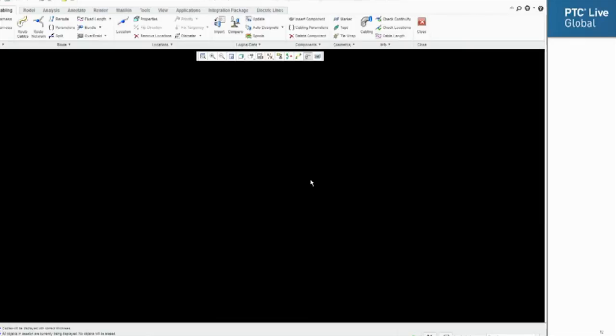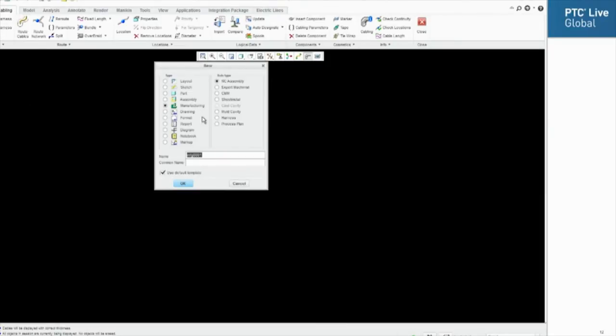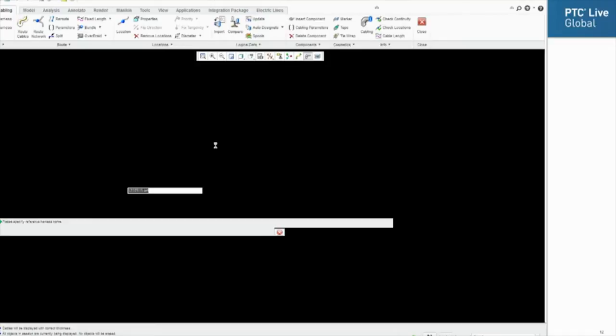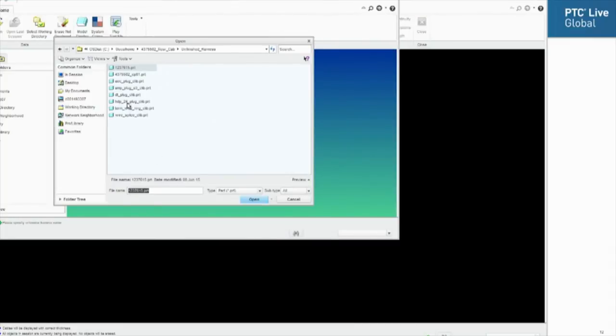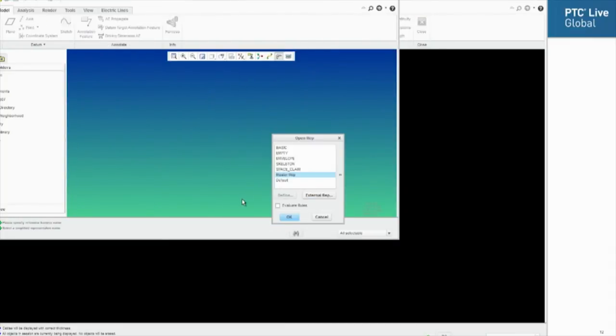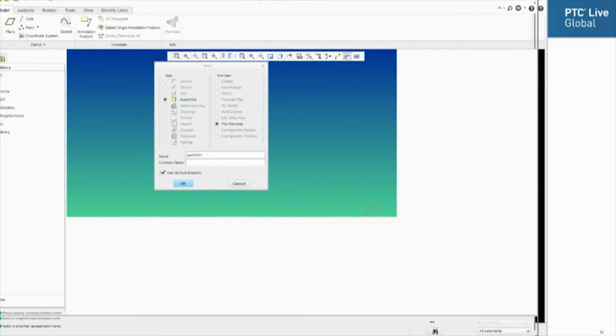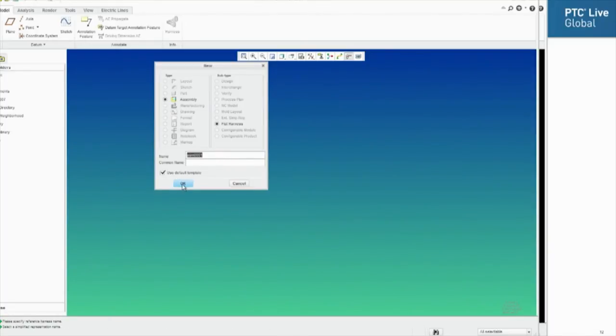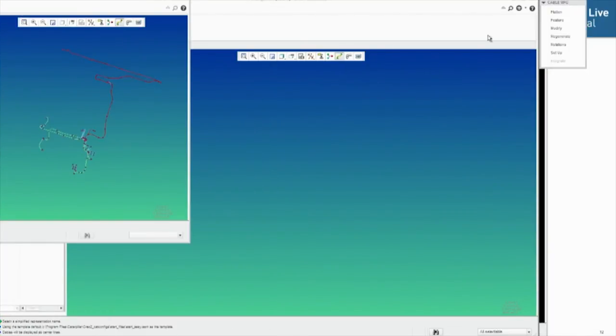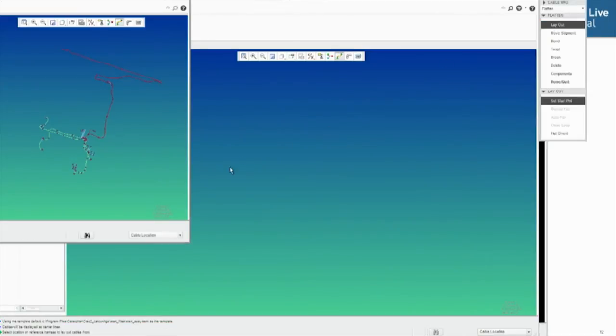It feels kind of funny to do. Guys like Frank make it easy because he goes ahead and defines the problem for me before I even ask. So I'm going to give my flattened model a name and choose my harness part. Now I'm going to go flatten layout, so select my start point, go in.